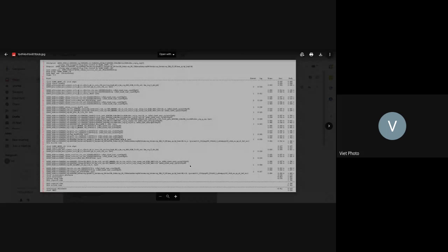That's called uncertainty. That's the margin. Let's say clock 1 is 1 nanosecond, but clock 2 can be 1.1 or 0.9 nanosecond, right? So we can see the difference between them can be like 100 picosecond. With that, we cannot be sure when it will happen. Clock 2 can happen anywhere from 900 picosecond to 1.1 nanosecond.